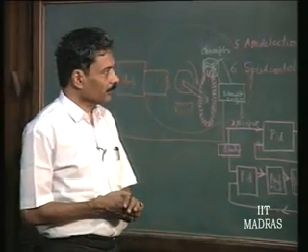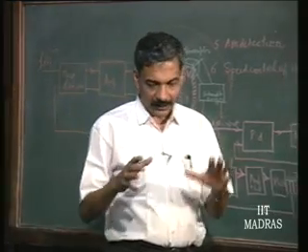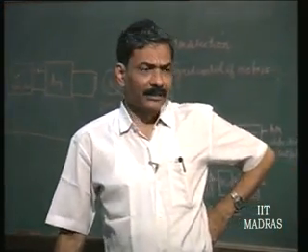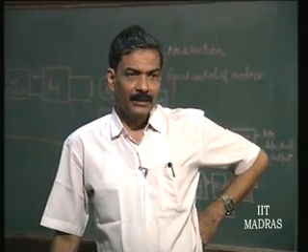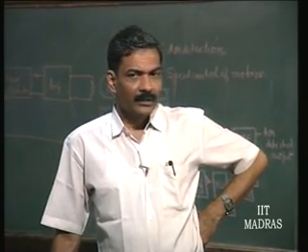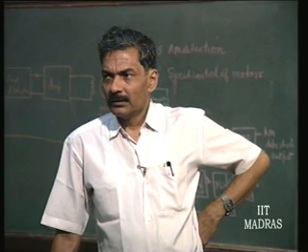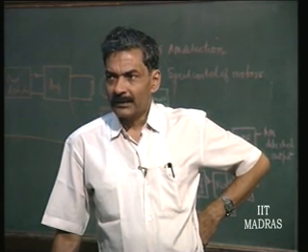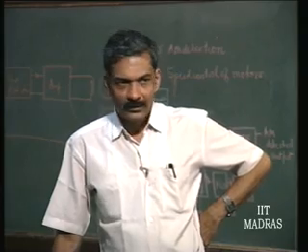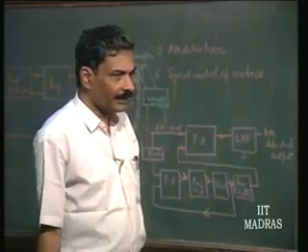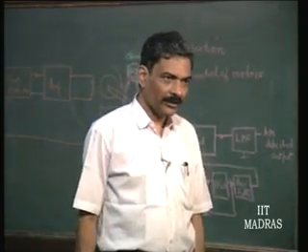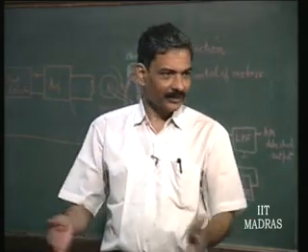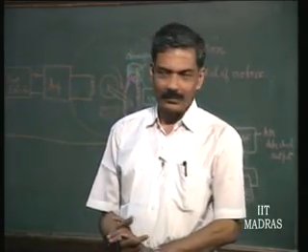Now, these are the important applications of phase lock loop. There are lots of other applications which are minor. For example, phase lock loop by its very nature, okay, can modulate what? Phase itself, obviously. It is a subtle difference between frequency modulation and phase modulation. Even though they are linearly related, if you do phase modulation, you get a frequency modulated output.